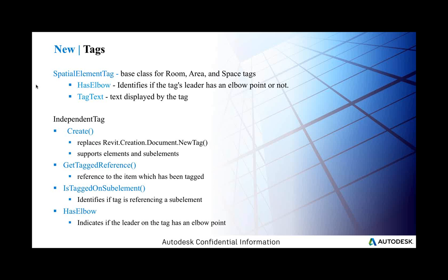The independent tag has been restructured, rewritten. So we have a new static create method, which replaces the Revit creation document new tag method. And this is something we've seen numerous times in the past. Every time this happens, it means that a lot of really old Revit API functionality has been replaced, rewritten, and we now have better access to the real underlying Revit database elements.